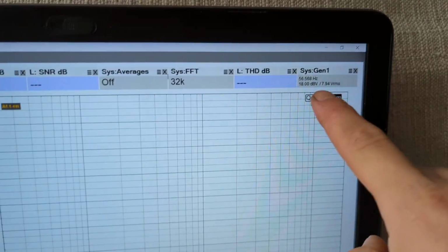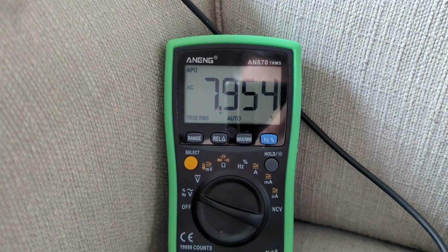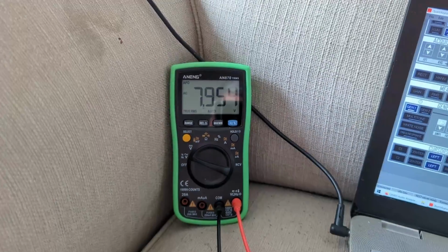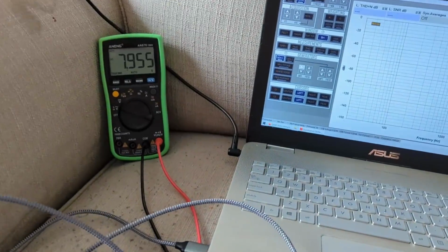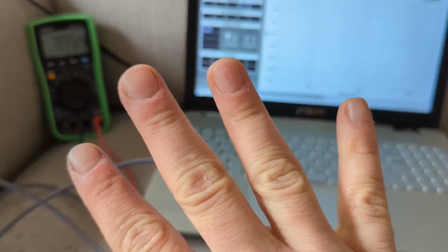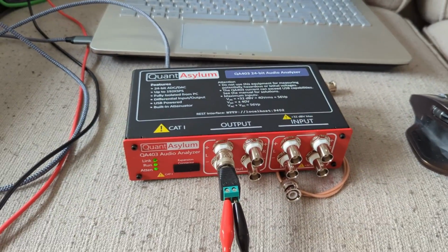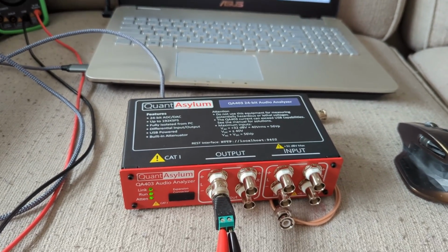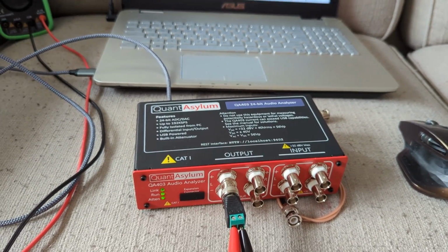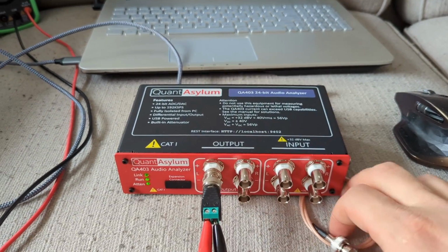And it goes up to plus 18 dBV, 7.94, 7.95 RMS. That's very, very close to 8 volts. This is exactly what I mean. It's overkill for amplifiers, because for amplifiers you need only 4 volts. But having 8 is even better, because some amplifiers do need 8 volts to max out the gain. So one of the Alpines that I've tested, and I believe Zapcos probably even need more than that. So having 8 volts on tap is great for amplifiers.